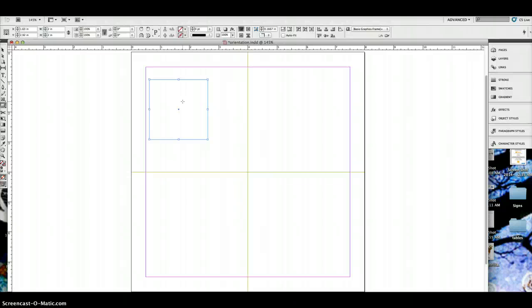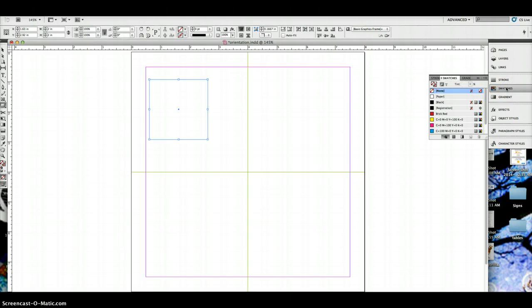So now that we've done that, click the swatches in the stack of collapsed panels to open the swatch panel. So again, go ahead over there and open swatches. Verify that the fill button is activated. Right here, this is the fill. This one's the stroke. We want to have the fill on top. And click the green in the swatch color. You may need to scroll to find it. And you'll notice then that your rectangle is shaded green.